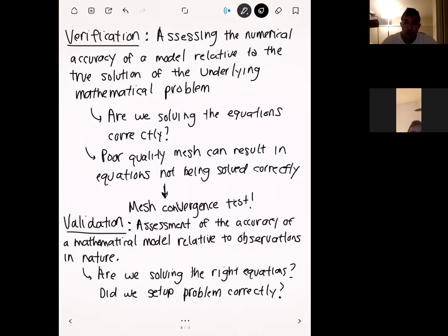And so, let's say that you're solving a structural problem, but you know that you need to include some nonlinear dynamics or maybe some buckling, right? And so there are very specific functions within Ansys that enable things like nonlinear deformation or buckling, right? And so if you think those things are going to be a big part of your solution, then you need to make sure you enable those features within Ansys in order to set those up, right?